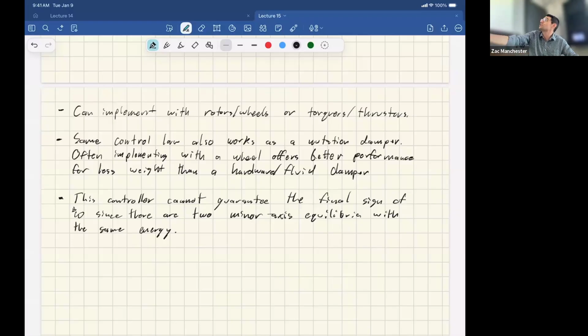So here's the one we just did, which is this kind of quadratic Lyapunov function. This is rewritten in terms of angular momentum, but it's just trying to drive the energy up, right? So this is just the energy we wrote down with a minus sign in front of it so that it's trying to drive it to zero, and then this is a constant offset such that it has a minimum at zero. So this is just me massaging the argument we just made into an official Lyapunov proof where the minimum's at zero and we're minimizing instead of maximizing.